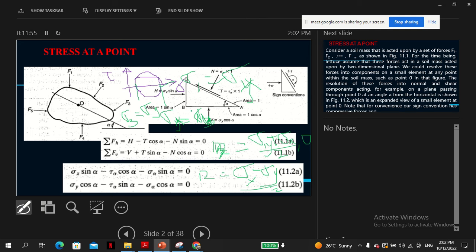And one more important thing is this angle alpha can be measured once you know what is called the pole. So say the pole is here. I'm going to explain that later. So you can just measure the angle alpha there. These readings here, this reading of tau and this reading of sigma, are the sigma alpha and tau alpha.